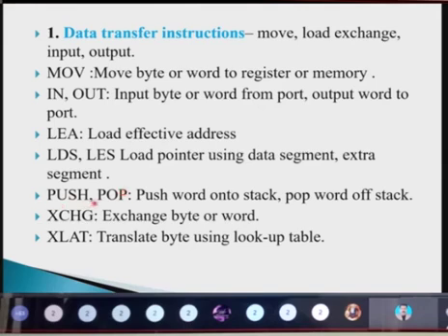This is about the instructions push and pop. And XCHG, with which we can exchange the byte or word. And XLAT, which will translate the byte using our lookup table.